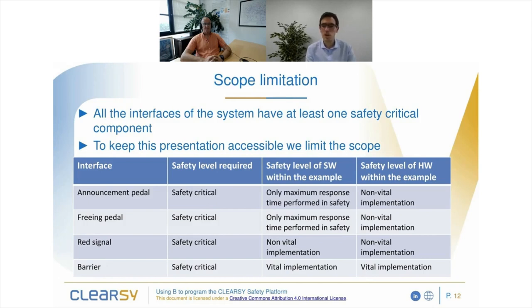So the barrier will be controlled through real industrial hardware that can ensure a SIL4 level, so the highest integrity level. In terms of software, the management of the barrier will be done through a fully vital implementation. And for the input, we will only focus on the guarantee of timings. As the underlying hardware is non-vital, it does not really make sense to develop safety critical software for non-safety critical hardware input circuitry.